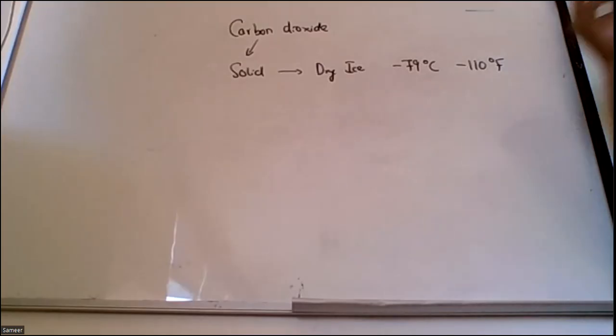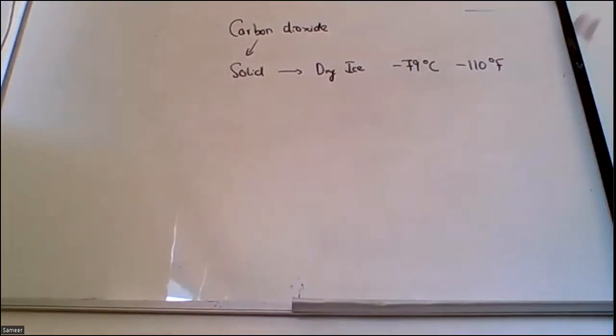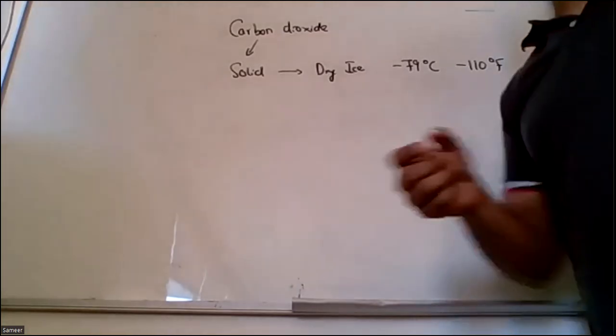It is always stored in the liquefied form. That is why whenever we are doing the maintenance of the carbon dioxide systems, as per NFPA 10 and 12, we usually check the weight of the carbon dioxide, right? If it's a gas, we will check the pressure only, because the pressure is the only thing that affects the gas concentration. Gas should always be pressurized, right? So liquid form, that's why we check the weight of carbon dioxide.